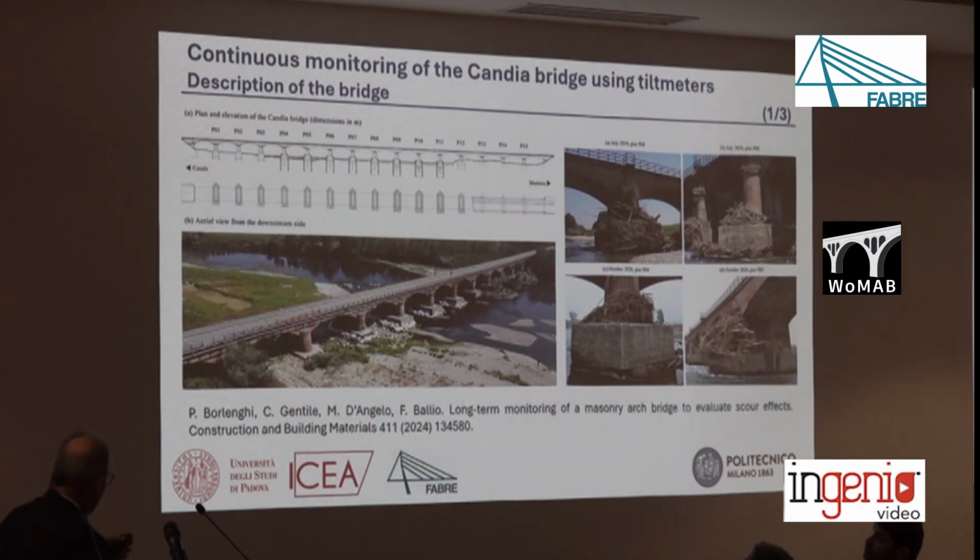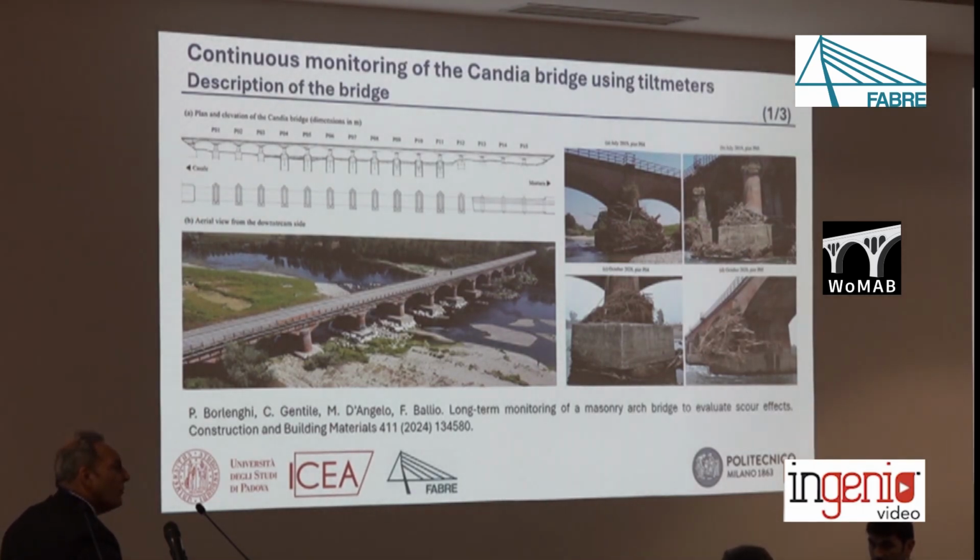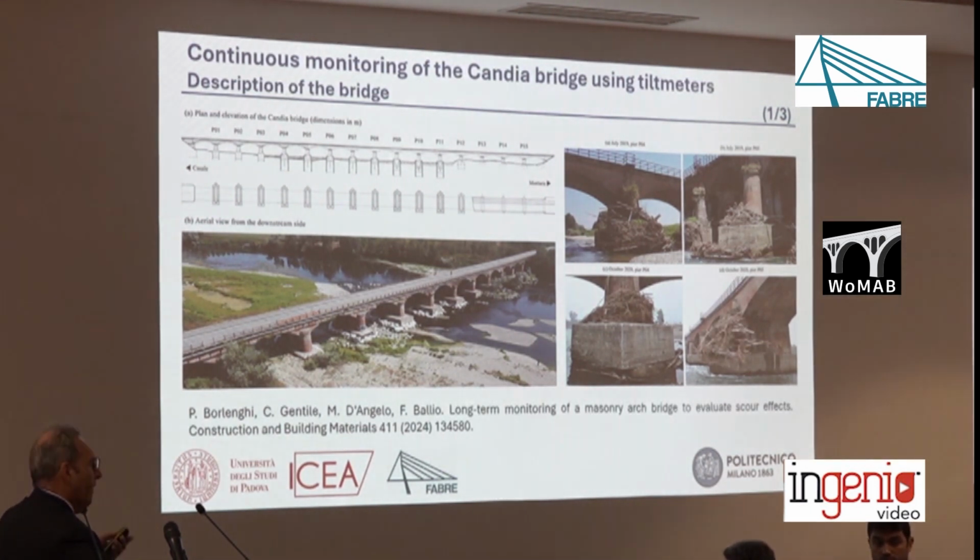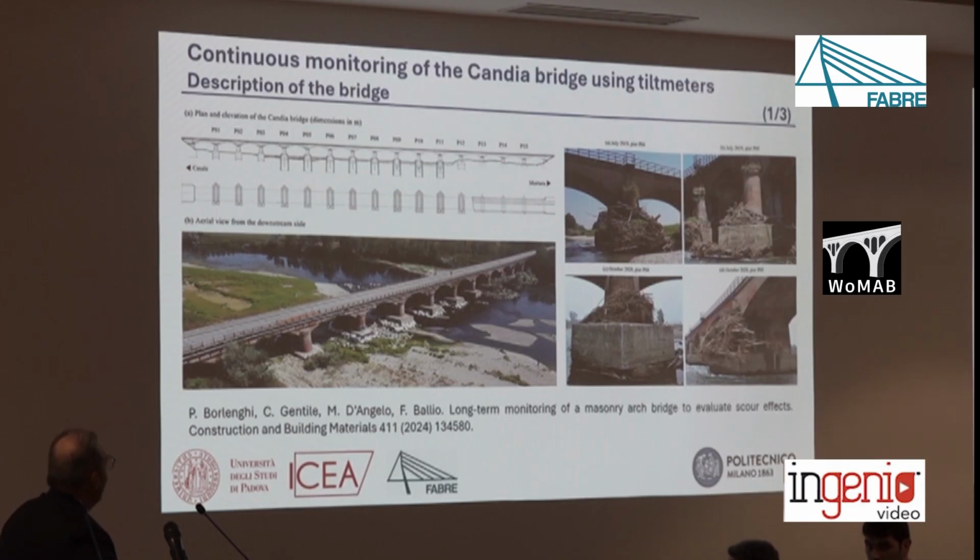Coming quite quickly to the last bridge, the investigation of this bridge was basically supported and also promoted by Lombardia region. Between 2018 and 2020, a research program was performed between Lombardy region and Politecnico di Milano, and in this project 9 pilot bridges were permanently instrumented with different objectives and also different systems. In this case, tilt meters were used.